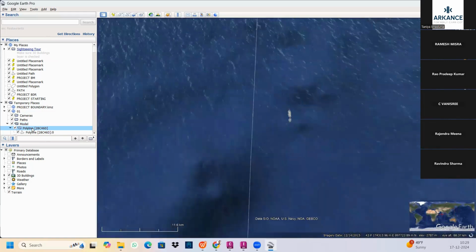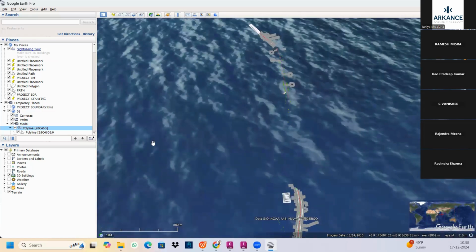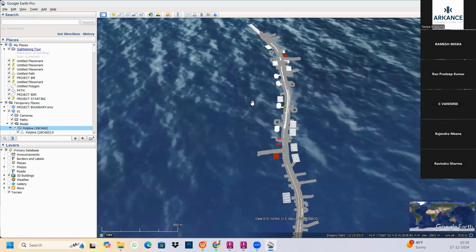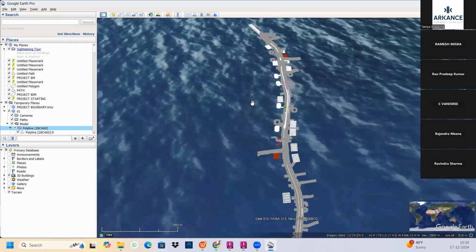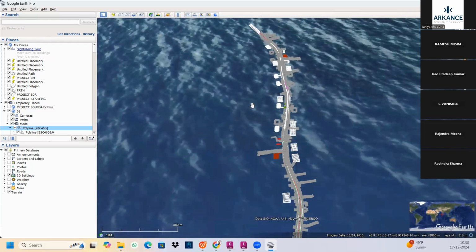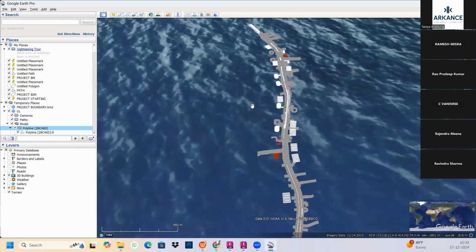Okay, no problem. I will check, sir, why it is coming only here. Ravindra, yeah, the probable reason could be the insertion units. You give the command INSUNITS and check what the insertion units are. If these are 0 or 6, then it will go to the perfect location.